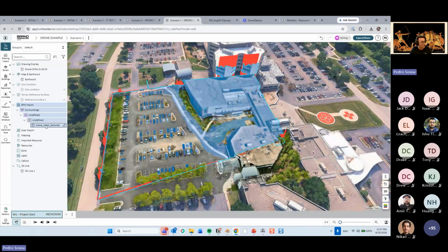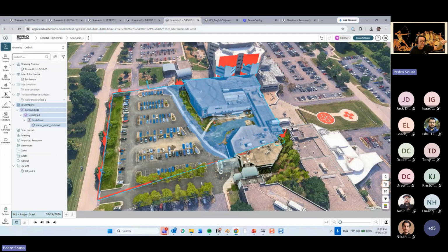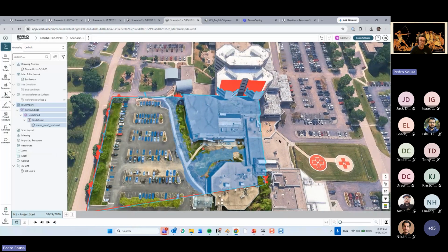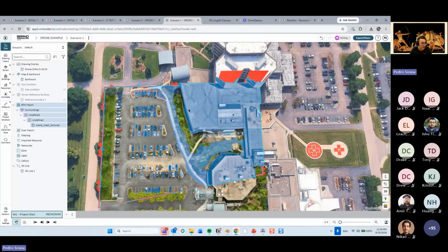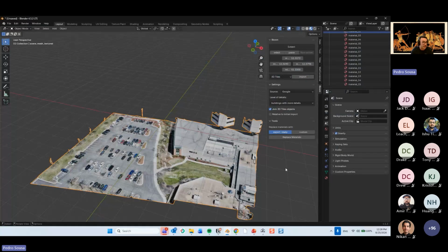So inside of this tree structure, I would have all of these materials that you see over here show up in my tree structure as different elements for me to select. This is not a big problem until you have to split the model. If I had to split the model, I would need to keep selecting all of those materials, and I wouldn't have combined shapes for me to work with. If I were to select to split this building over here only, I would have several parts that would compose this building. So how do we fix that?